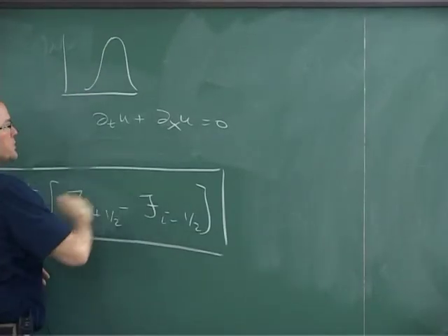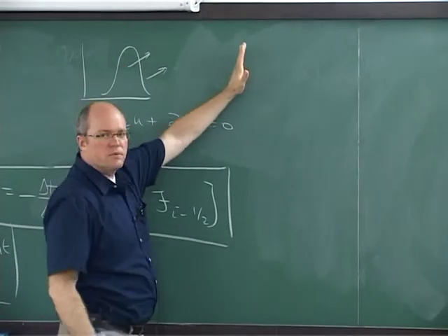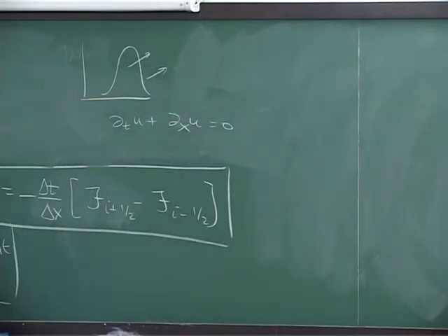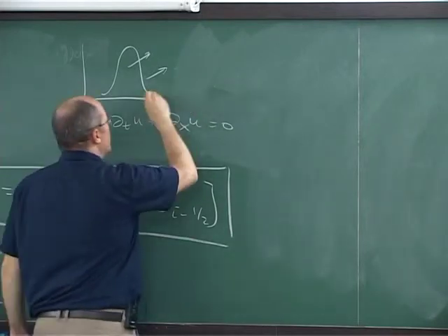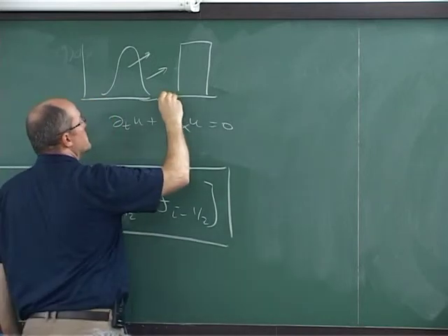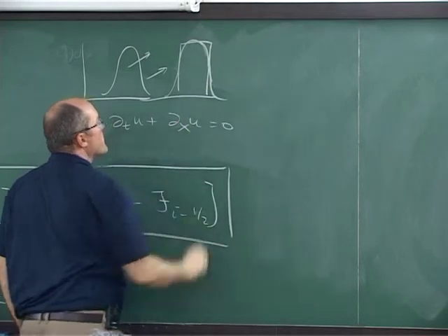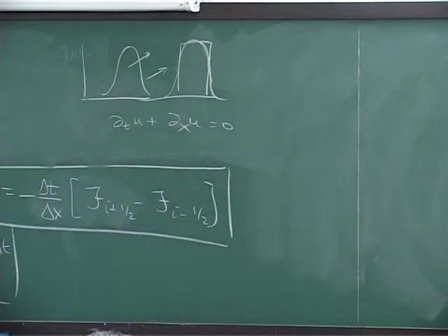We put on some function here, and the characteristics are constant, and so this just moves to the right, correct? And you found that if I made that discontinuous or had sharp features, the upwind method did best, and the numerical solution looked kind of like that. I kind of smeared it out, but otherwise I did okay.